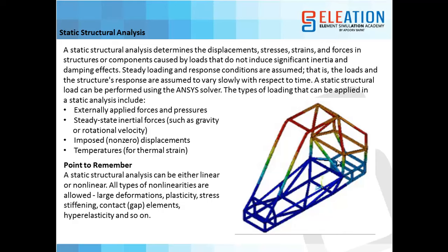A static structural analysis can be performed using the ANSYS solver. The types of loading that can be applied in a static analysis include externally applied forces and pressure, steady state inertia forces such as gravity or rotational velocity, and imposed non-zero displacement or temperature for thermal strain.